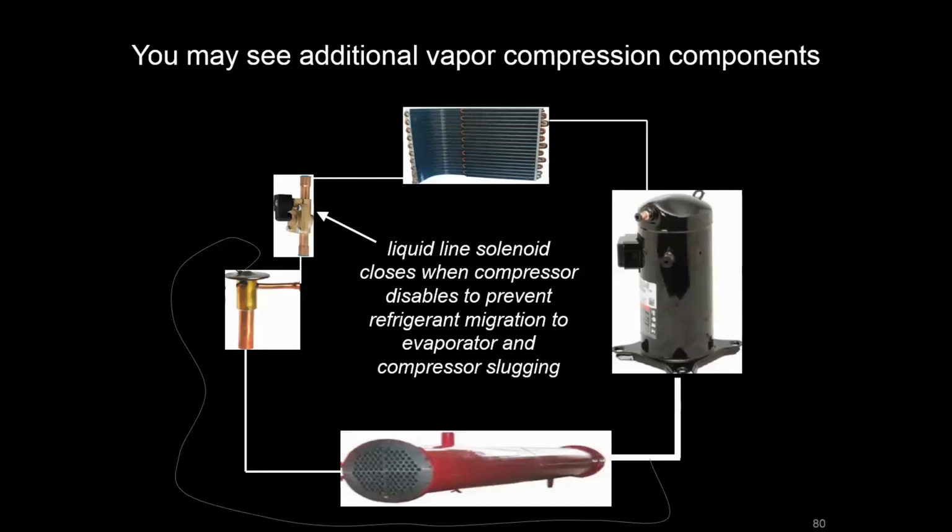And the intent there is that you don't have refrigerant that is going to migrate through your condenser towards your compressor and have a condition called slugging, which is when you have liquid real close or right at the compressor. When that turns on, that compressor is going to bang against that incompressible liquid and almost consider it like a water hammer situation, and that's going to cause a real loud mechanical bang, maybe vibration, and it can damage your components or blow out some of the seals in your refrigerant line.